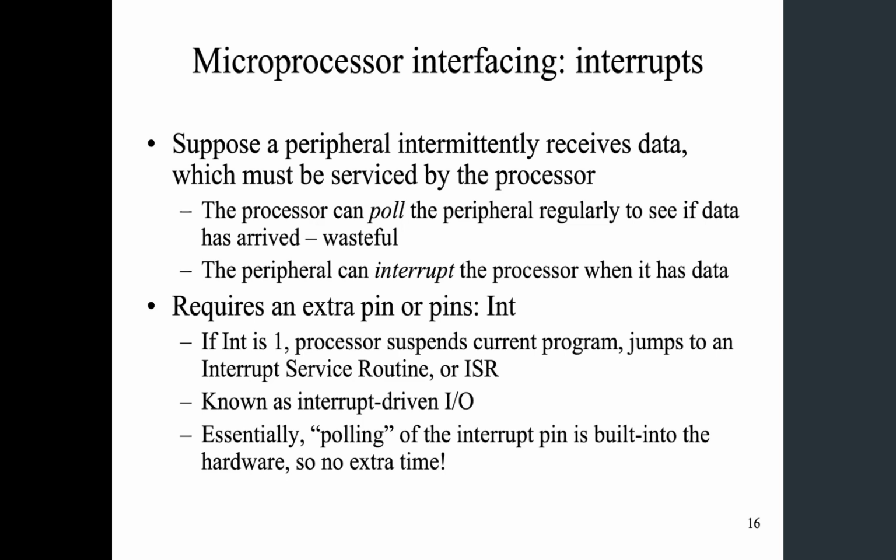That means it has to use instructions to keep checking the status of the peripheral and check, are you ready, or do you have data? Do you have data? If you do, then we'll go ahead and read. But if you do the polling, you're actually going to spend a lot of CPU cycles on doing that instead of doing something more useful otherwise. That's why we have this concept of interrupt.